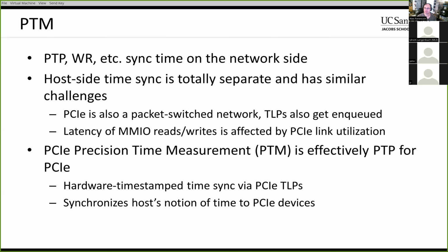And it basically works like PTP and uses PTP boundary clocks at all of the PCIe switches. And this enables a host's notion of time on the CPU to be transferred to the PCI Express devices.